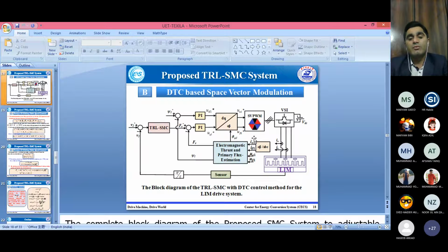For example, when we talk about the chattering in the system, if there is a higher chattering, you can feel some vibration in the metro. If it is connected with, for example, a hoist or lift, you can feel some vibration. This is due to the chattering. For the ripple, when you talk about filters, if there is no filter, your system would be heating if there is a higher ripple in the current.